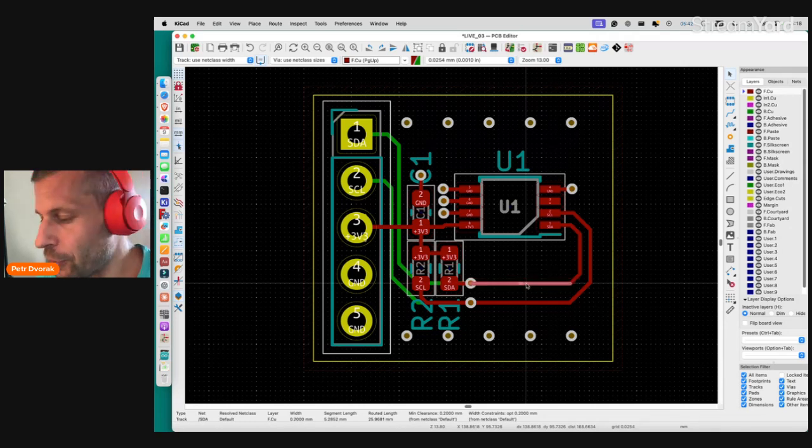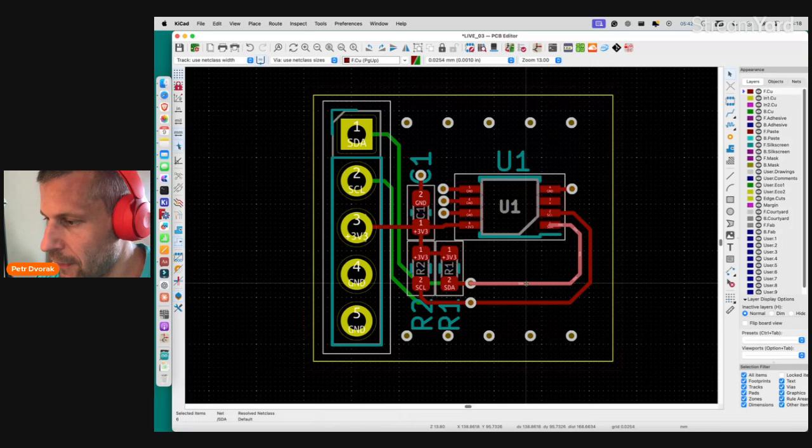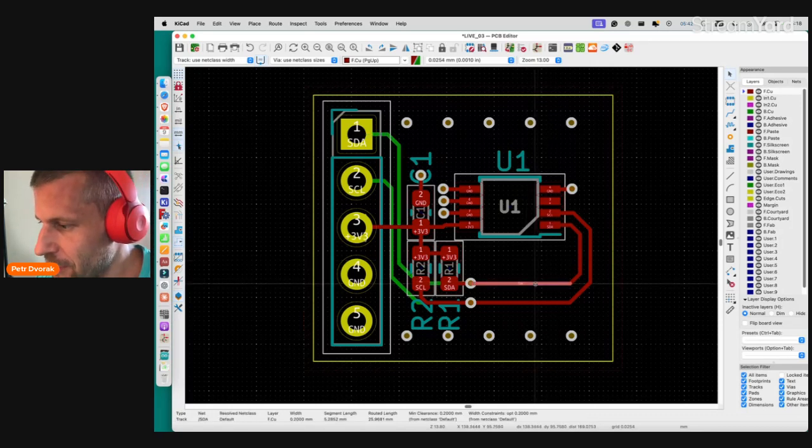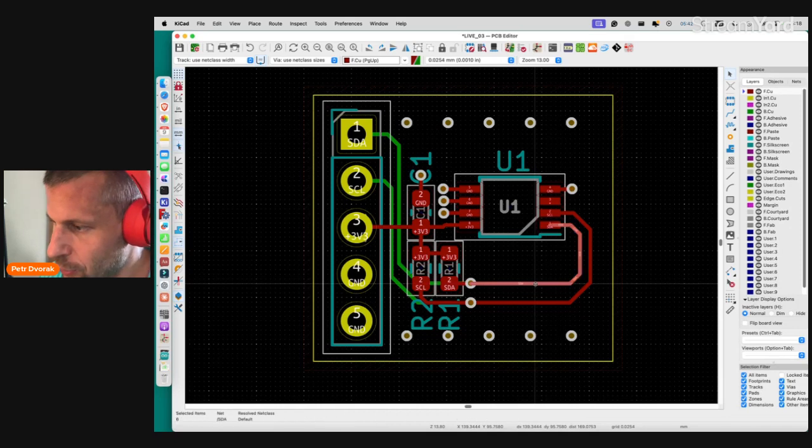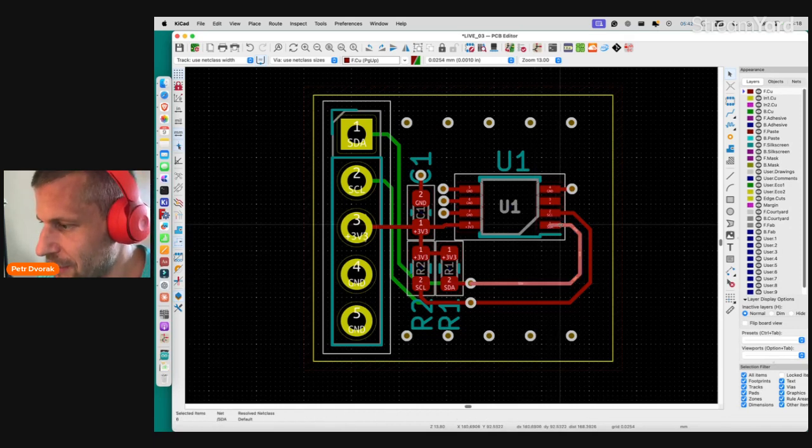For instance, you want to change the thickness of the entire segment. So press U as many times as possible. You can see when I start with this segment and press U, the segment between the nearest footprint and the nearest object like a via or footprint is selected.